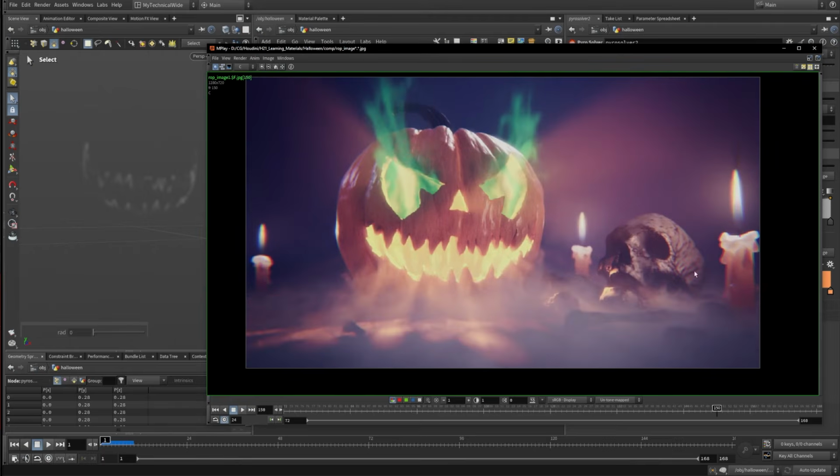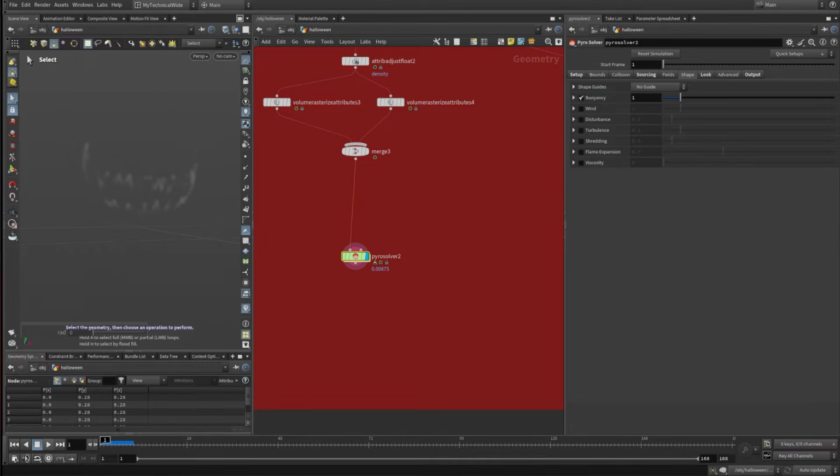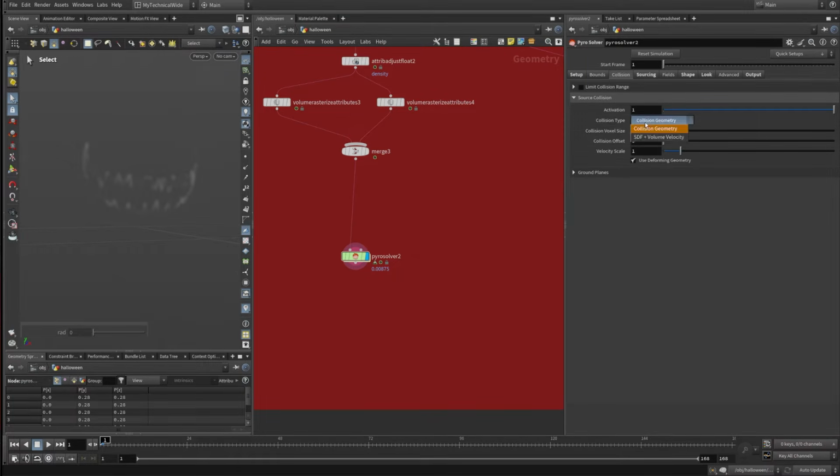It's like more magical. So a simple way to simulate something like a dry ice is, again, we can go to buoyancy, and in the first example where we had the ice, we just reduced the buoyancy 10 times. In this example, I will negate the buoyancy. I will make it -1. If I make it -1, the smoke will be just going downward. Right, and if we make this not as strong, so -1 divided by 2, and then if we add some ground collision, this will start looking more like a dry ice.